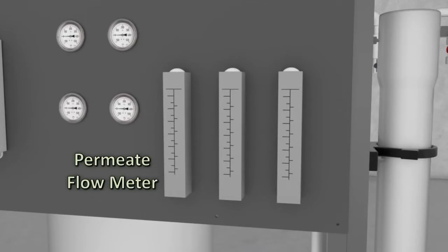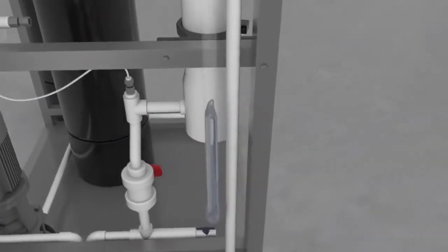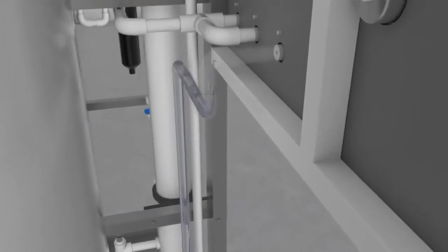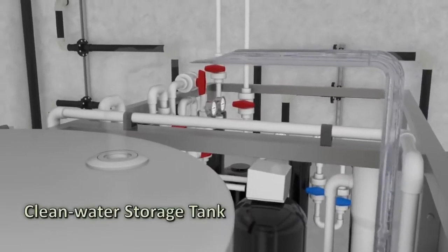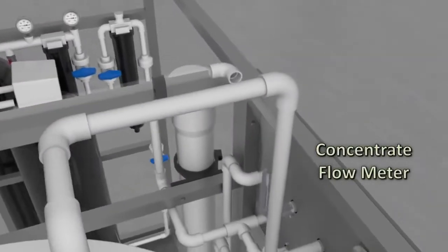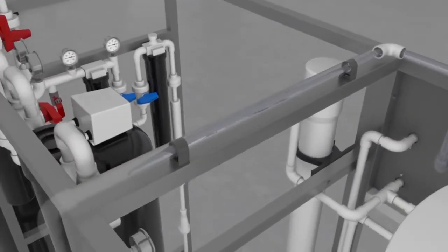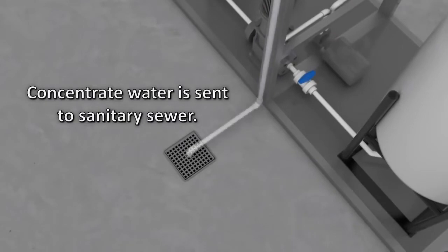The permeate water, which is the clean, filtered, or product water, passes through the permeate flow meter and is sent to the product water storage tank. At higher salt levels, the concentrate is sent to sanitary sewer, or in some cases non-critical locations for reuse, also known as gray water recycle.